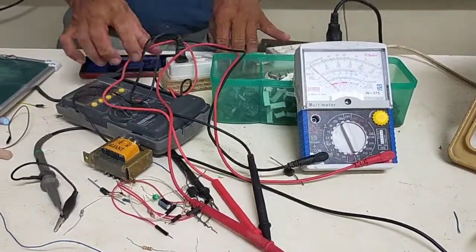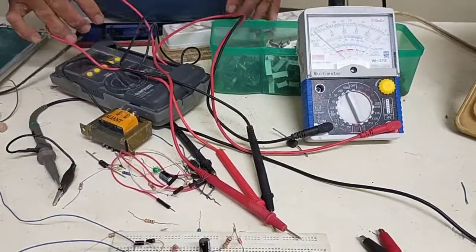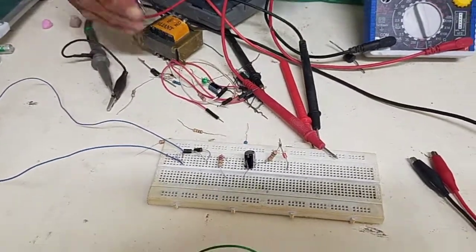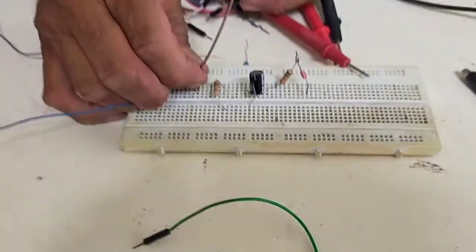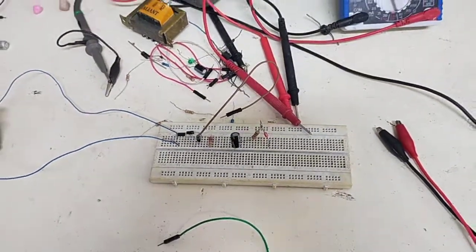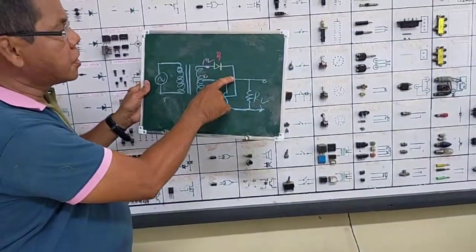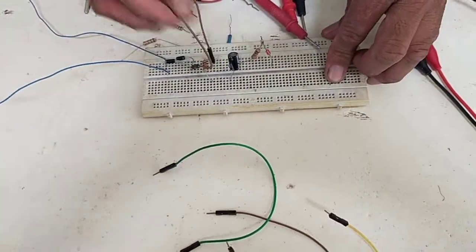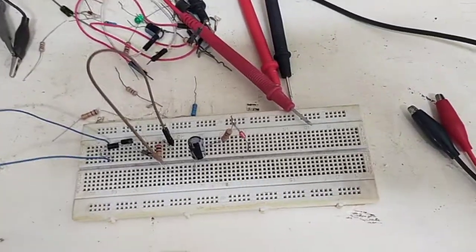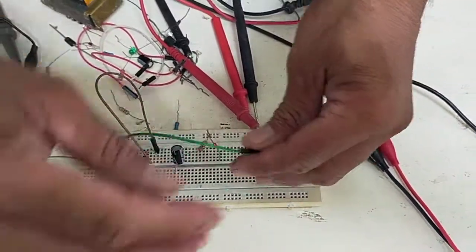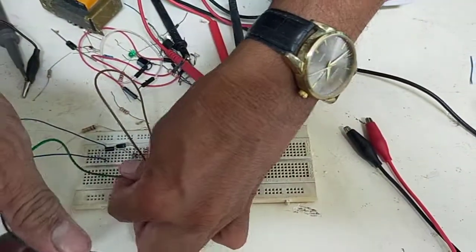Let us first disconnect the power supply. Now, connect. The two cathodes are connected together, and connect them to the resistor of 2.7 kilo ohms. Whereas, the other terminal of the resistor is connected to the center tap.